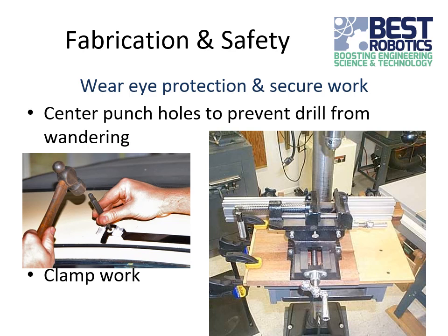Center punches are really cheap. There are spring-loaded ones or ones you just hit with a hammer. You can sometimes get away with using a nail, but it's a good idea to have an actual center punch.